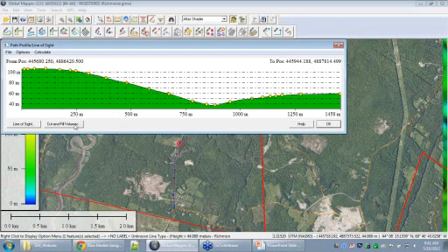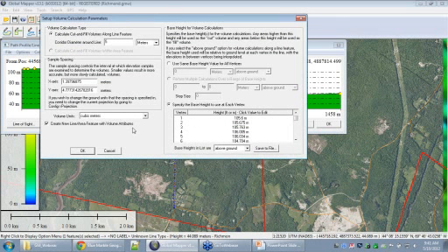If we need to know how much we're going to dig out going along, following that terrain, we can do a cut and fill volume calculation. So let's say we're going to make our road, do this in feet since we're in the U.S. I'm going to make the corridor diameter around our line about 20 feet across. So our road is going to be 20 feet wide, and we want to establish our volume units.